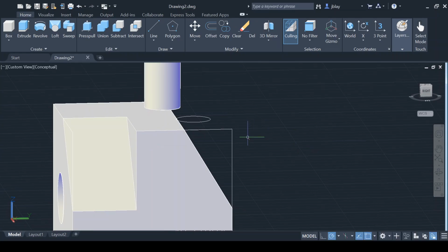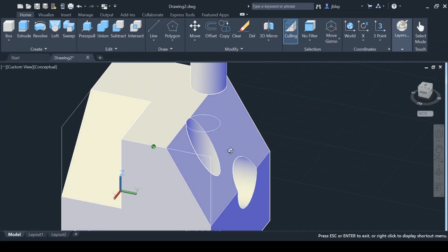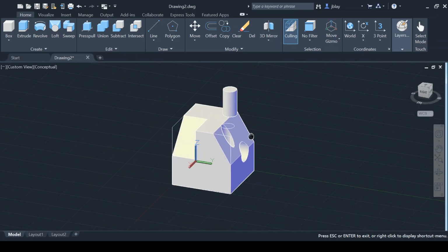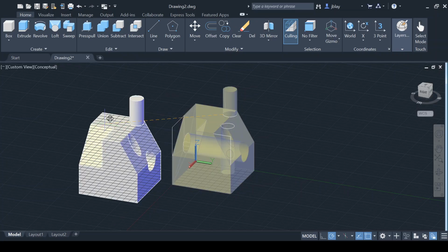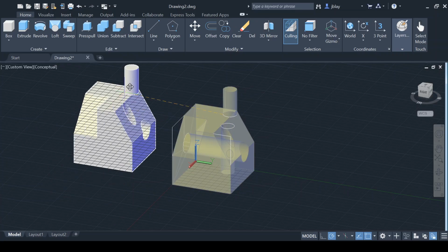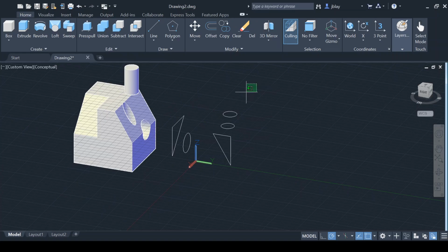Okay. Oh, and the last thing I wanted to mention, I already said the last thing, is press pull, unlike extrude, leaves these lines behind that you used to create your intrusion or extrusion. So you want to make sure you get rid of those. What you want to do to get rid of those really easily, you can go through and select all of them, but I think it's a lot easier to use the command move. So you type in move, hit enter, select your object, hit enter, select the base point, move the shape out of the way, and then select all of these lines and delete them.